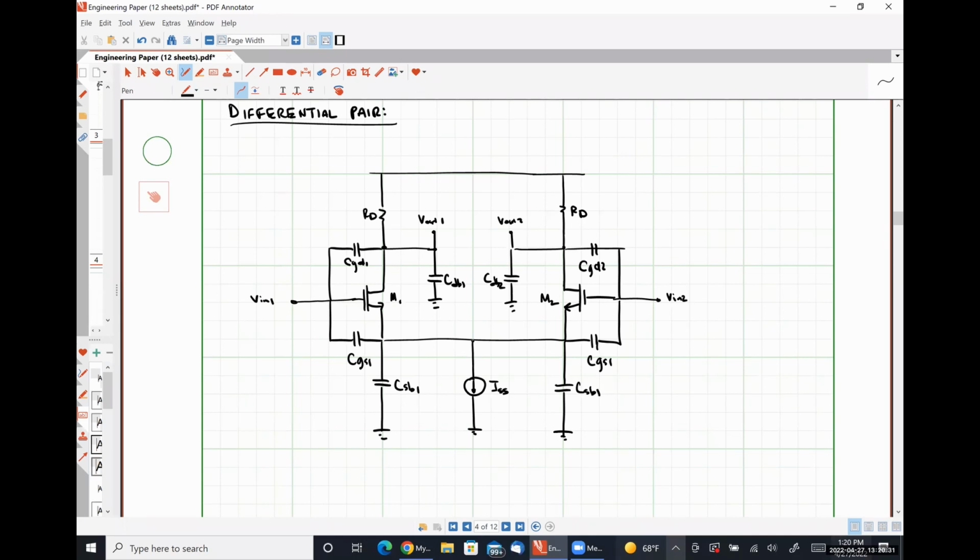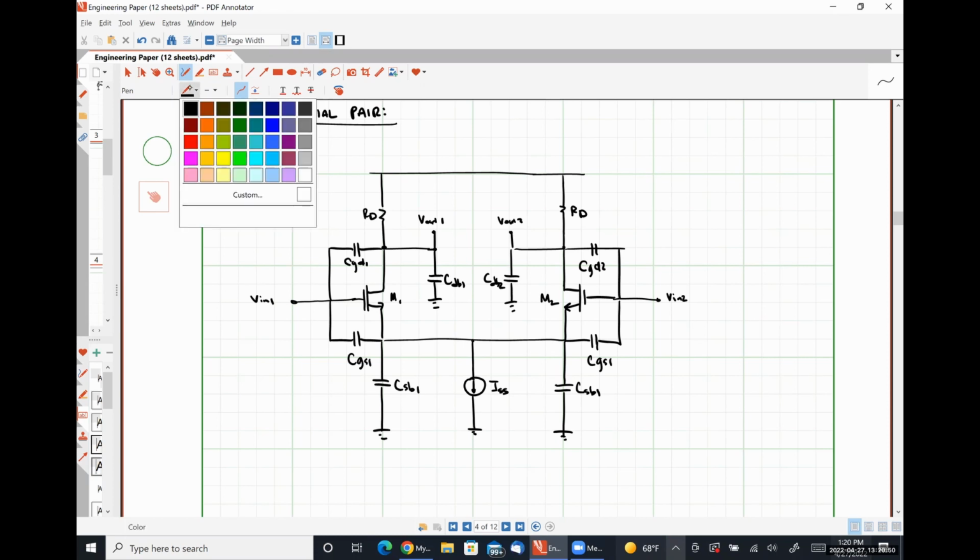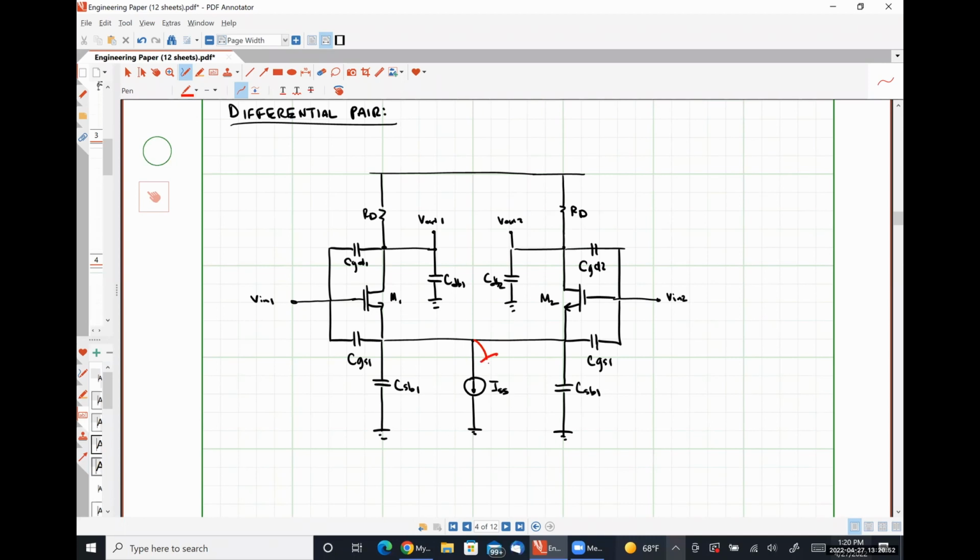All right, so let me ask you guys a very important question here. Is this circuit symmetric? So that means that we know that this node is a small signal ground, right? Because when we have a symmetrical circuit, this floating potential in the zero has to exactly balance out. All right, so